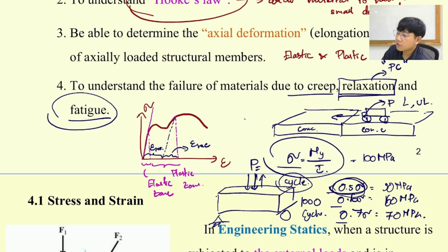For example, this road can last for 30 years. That 30 years comes from the fatigue test over here. It depends on the project. For example, if a project is built in a rural area and then they're going to have a development project later, they design the pavement to have a lifespan of only 10 years, and then 10 years later they're going to come back and develop that pavement again. So this is how we test the fatigue.